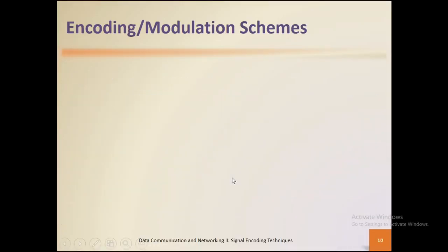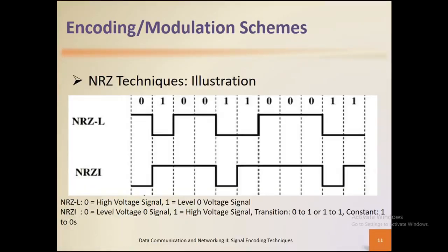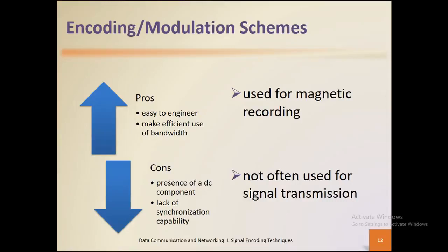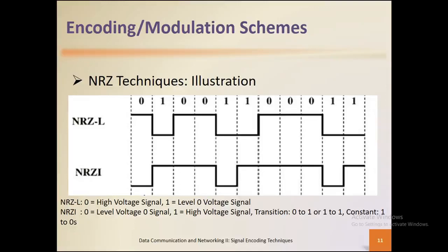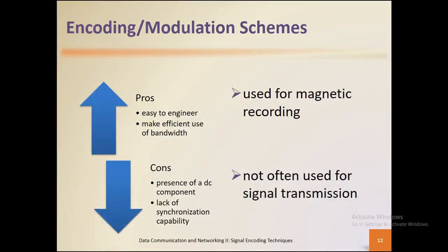Okay, let's move on to some of the pros and cons of using the non-return to zero techniques. Pros: they're easy to engineer, they make efficient use of bandwidth, and application-wise, I use the most in magnetic recording applications.